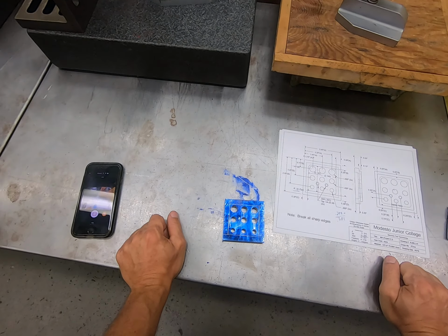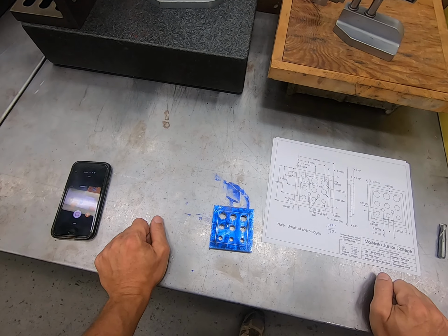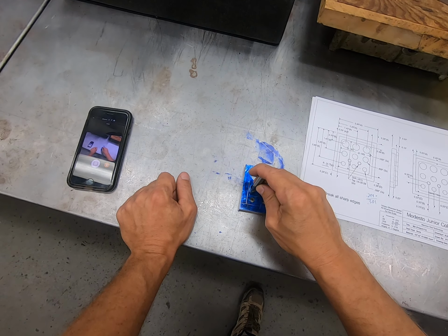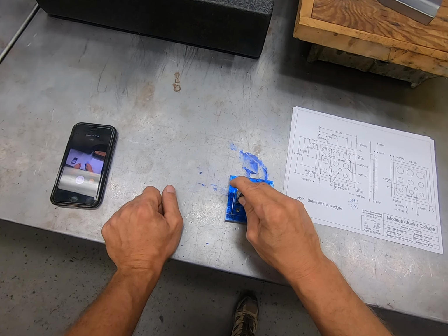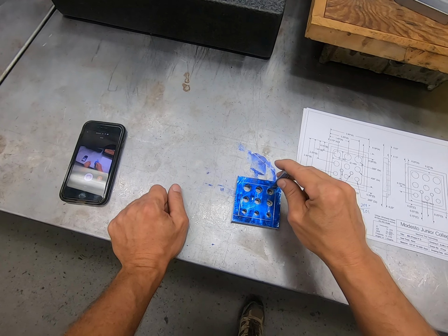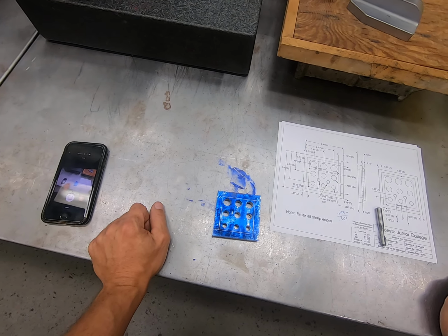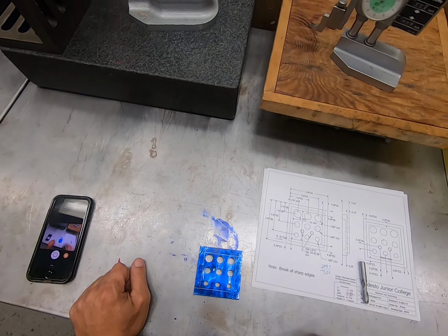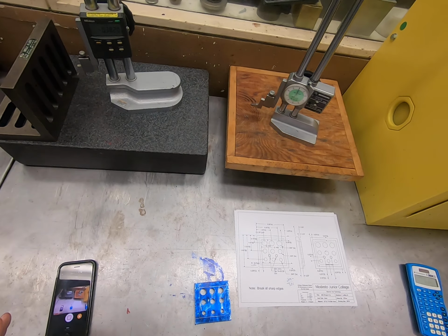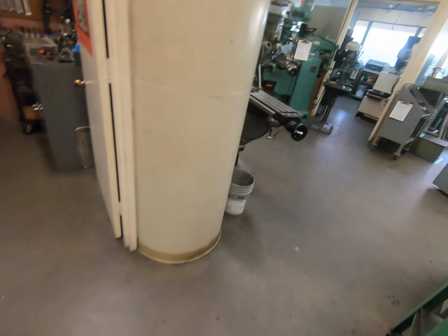So what we're going to do now is just visually machine and mill close to those lines. I don't want to mill all the way exactly up to it. I want to mill and leave maybe a 32nd of an inch, maybe a 64th or a 16th, away from that line so I can actually see the line still exists and I know that I'm on the inside of it. I'm going to do that manually and just visually. So that's our goal here, to get this roughed out inside of there, close to the lines. The lines are going to be pretty close too, but we're going to do some measurements to get those perfectly accurate. So we'll head over to the machine tool here.